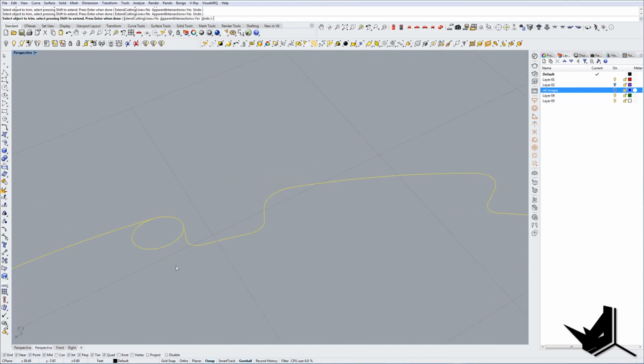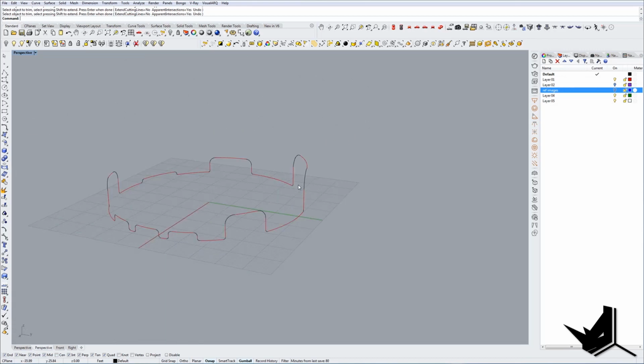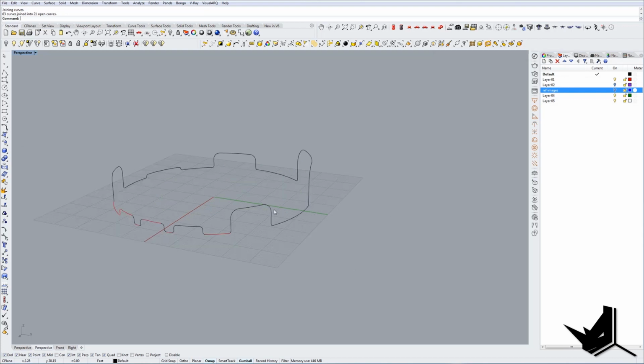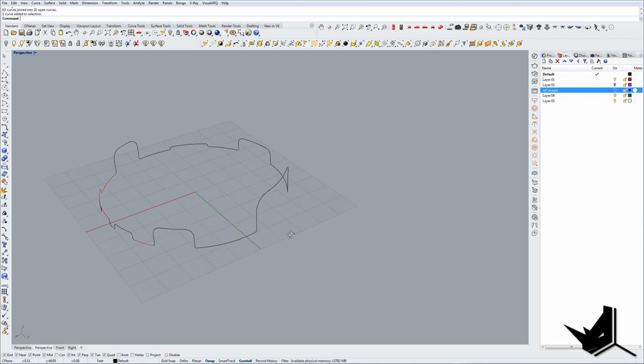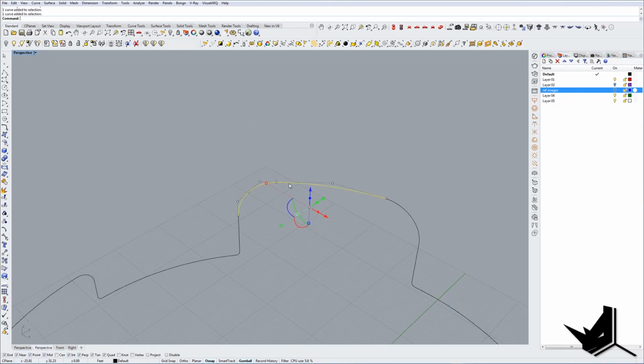And in addition to that, sometimes the trimming may not create the continuous line, which is what we need. So I'll just trim this out now and show you the progress later. All right, so now when the trimming is done, what I wanted to show is that if you just go like this, select everything and click join, you will see that some things will join, some things will not join. And that's because we need to actually manually fix some points.